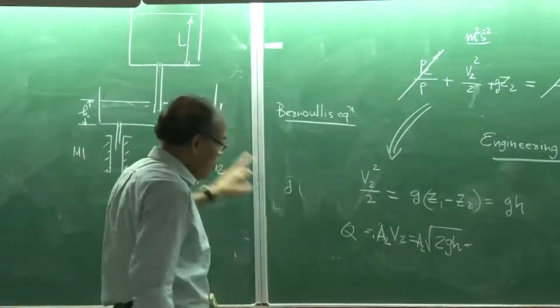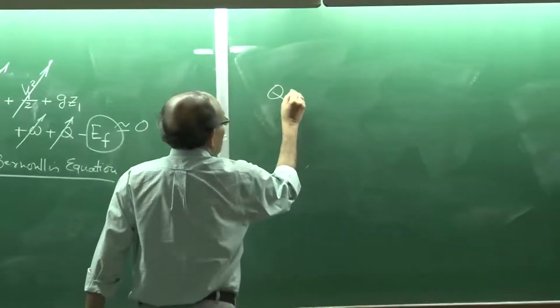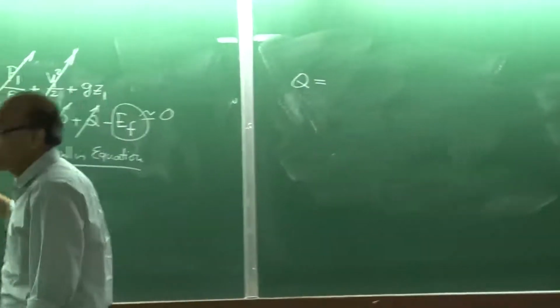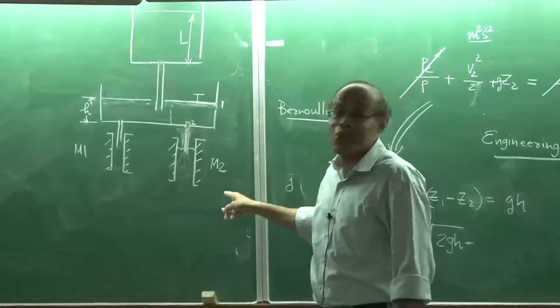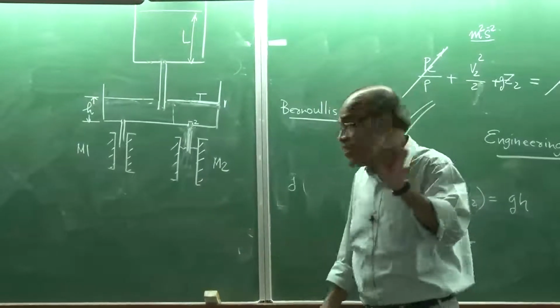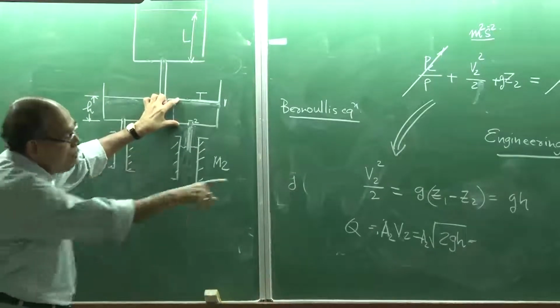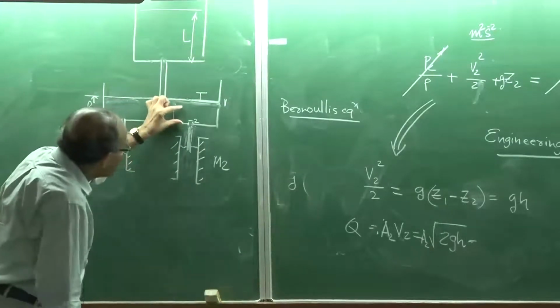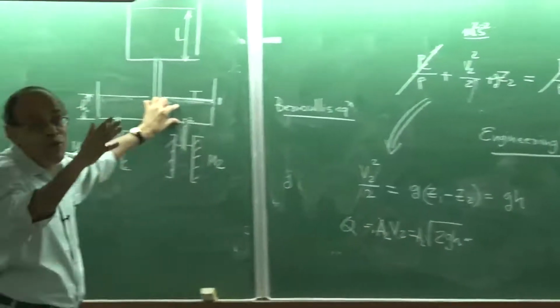In nozzles, for example, the volumetric flow rate applies under steady state condition. If the bath is changing, I cannot apply this particular formulation really, because I can find the instantaneous value when the bath depth is this much, then this applies. When the bath depth is this much, then I will have a different h value here. So, the velocity is going to be a function.